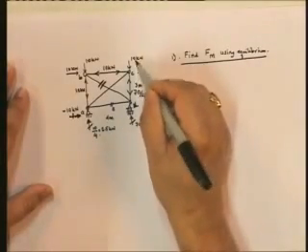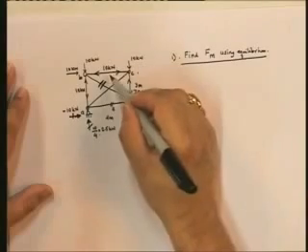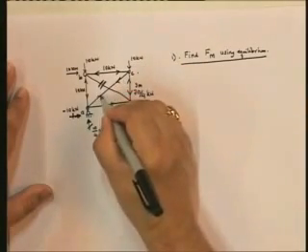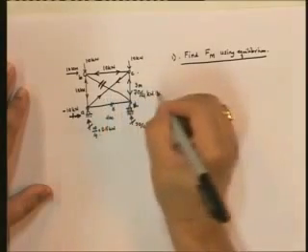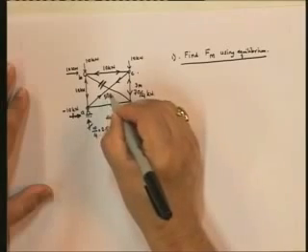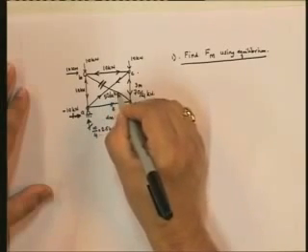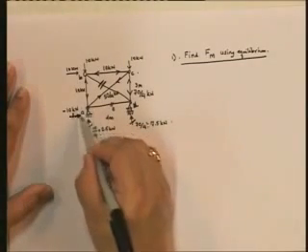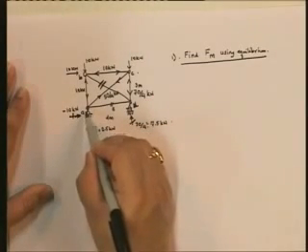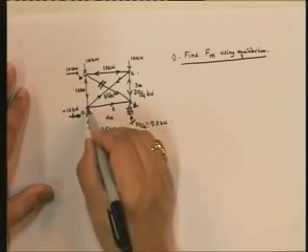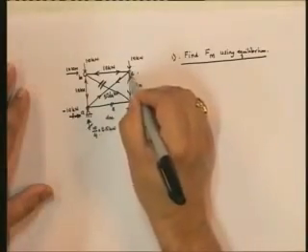And from that we can find out, actually if you go about it, you will see that this becomes 30 by 4 and 40 by 4, and so this is equal to a tension force of 50 by 4 kilonewtons. And now if you look at this particular situation, you will see that the equilibrium of this joint is satisfied automatically. And you will see also that the vertical of this is satisfied.